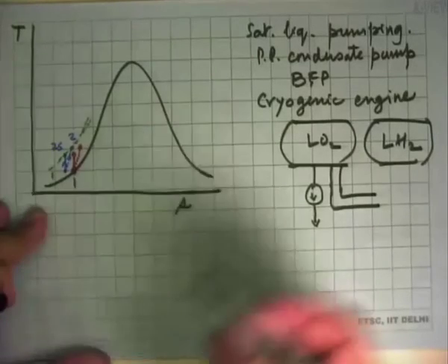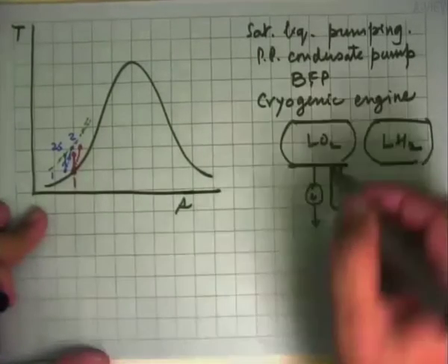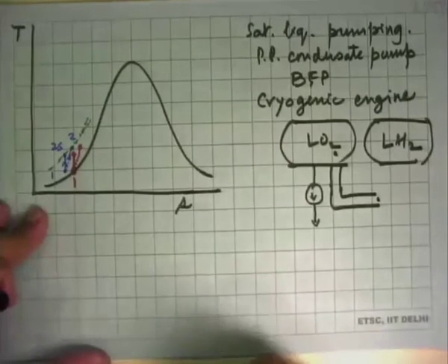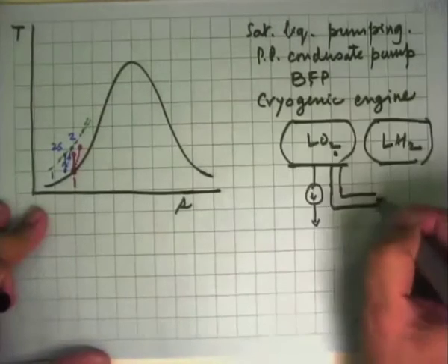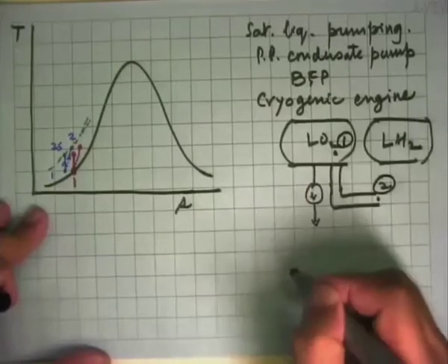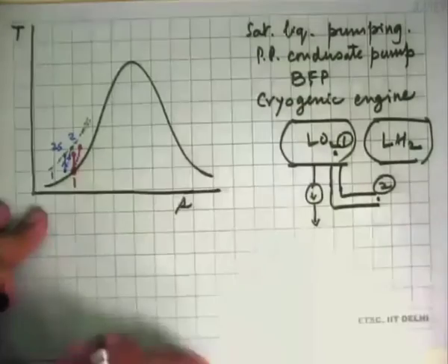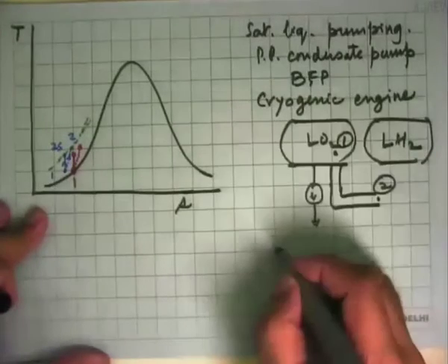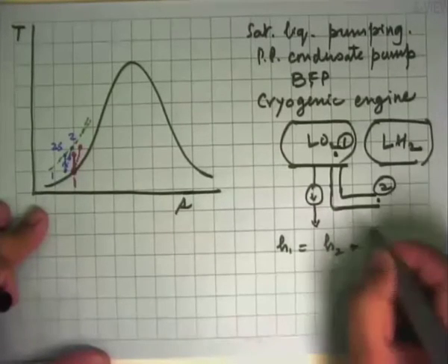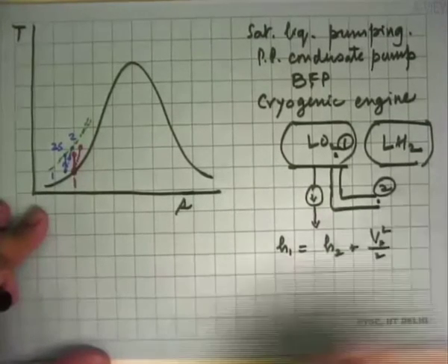then because its velocity is increased, and what we have learned from thermodynamics is that here and here, if I apply the first law, here velocity is 0, here velocity is finite. So this was state 1, this is state 2. All the assumptions of steady state flow we take, then H1 is equal to H2 plus V2 square by 2.